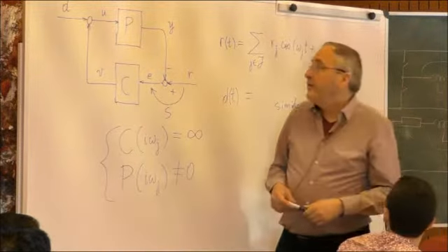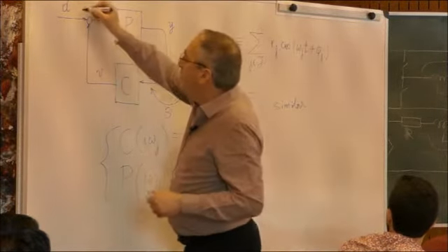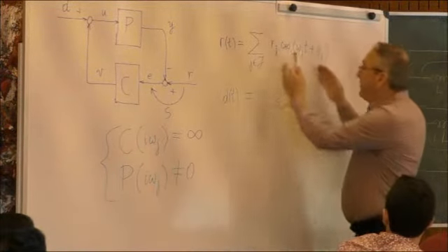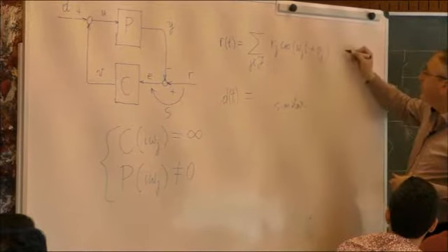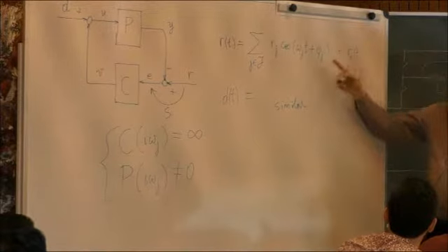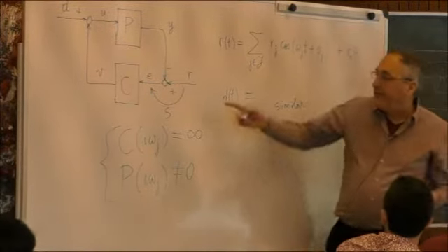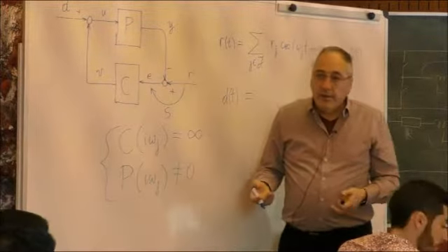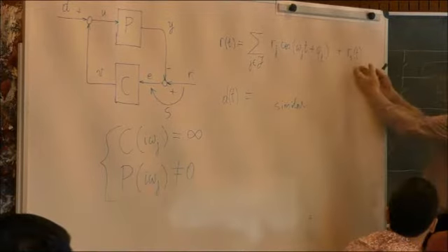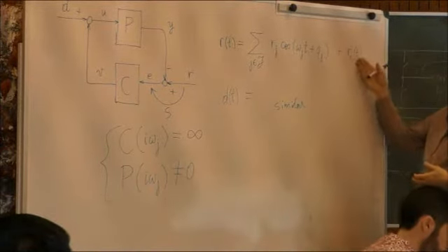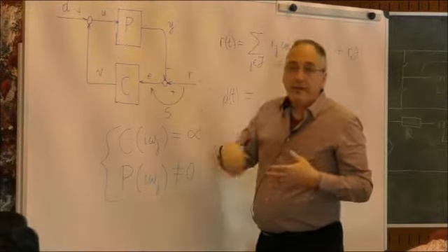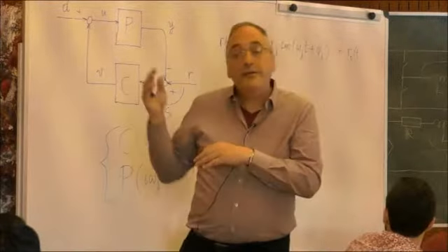Now, if the signals D and R contain components in addition to this, if there is some additional component, say R_0(t), which is not sinusoidal, then of course the steady state error will not tend to 0. And to defend also against whatever other noise there might be, we want in principle to make the controller gain as large as possible also at other frequencies.